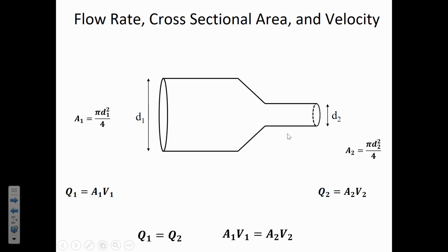So another way of having low pressure, besides like a vacuum bell, is in a transition like this, where you suddenly have very fast-moving fluid. That can cause the pressure to decrease to the point where the liquid can potentially begin to boil or cavitate. So something that we'll look at later in hydraulic engineering is preventing cavitation in cases where suddenly the velocity is much higher because of a cross-sectional area decreasing like this.